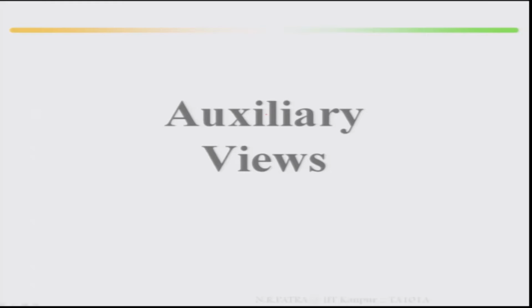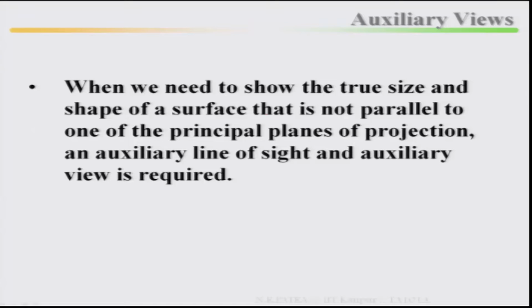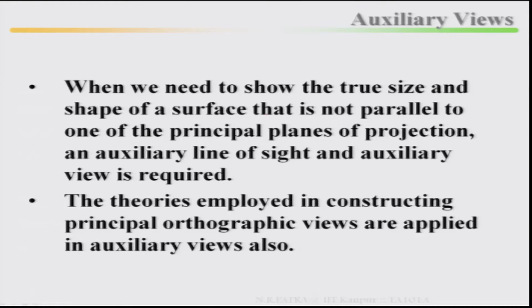Now, come to the auxiliary view. When we need to show the true size and shape of a surface that is not parallel to one of the principal planes of projection, an auxiliary line of sight and an auxiliary view is required. The theory employed in constructing principal orthographic views is applied in auxiliary views also.